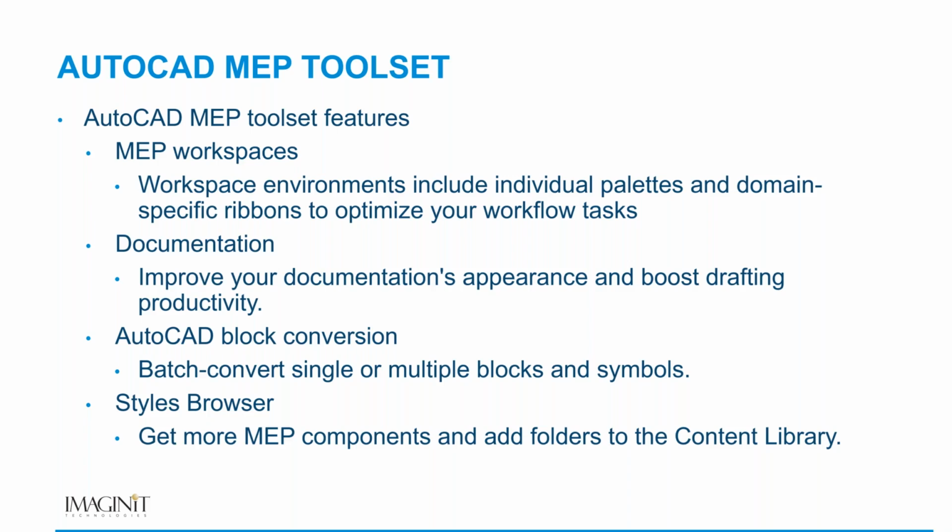And then your styles browser, you get more MEP components and can add folders and custom content to your own custom library, especially if you deal with any specialized stuff. You add that to your content library, and now you don't need to recreate it or go steal it from other drawings.